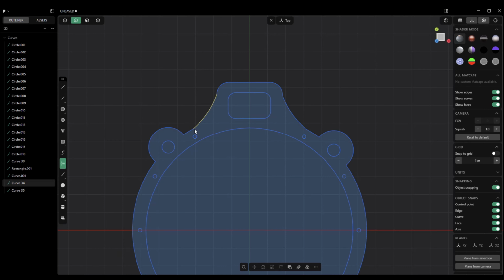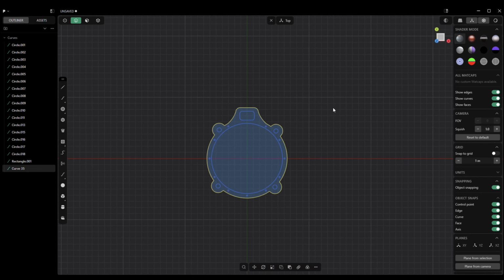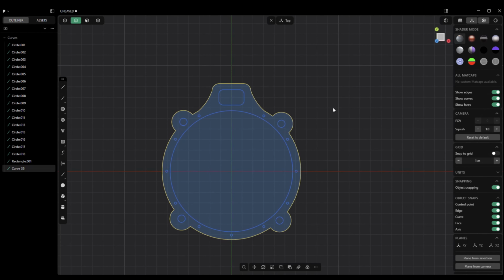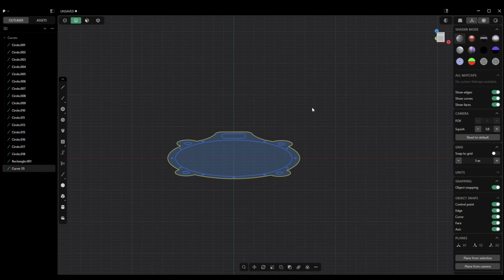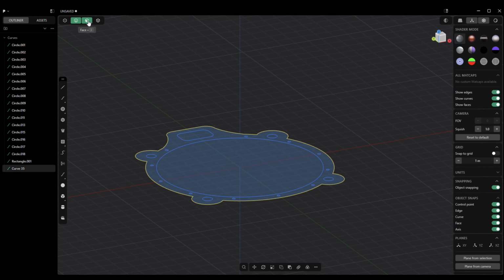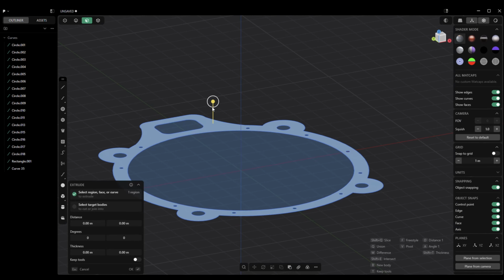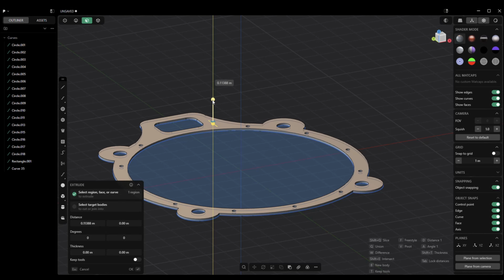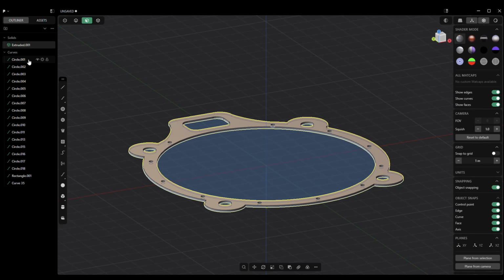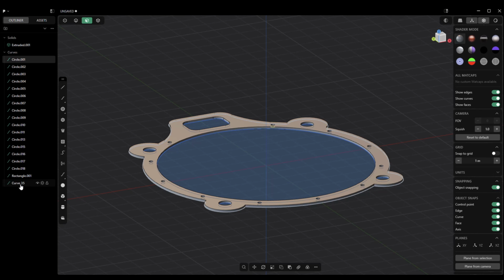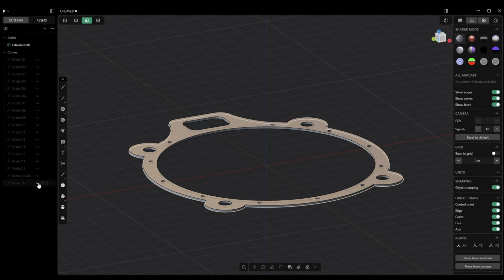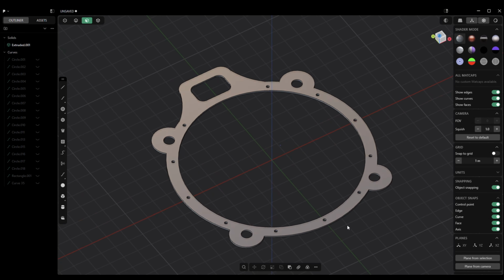So we're going to still my trim tool, sorry. So we're going to grab this, this, and this, and this, and if it's all good, we should be able to combine. And we can, right? Now at this point, you can make the actual gasket, right? So you just go in here, you go to face mode, you grab this section, and you raise that up till you have the desired height. Click on OK. Then you go in here and you select the entire row of curves and you hide them, and then you have your gasket, right?